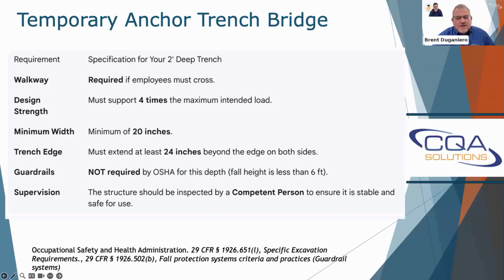The minimum width, you got to be at least 20 inches wide. The bridge must extend at least 24 inches on either side of the trench. I'm not sure either one of those met that requirement.